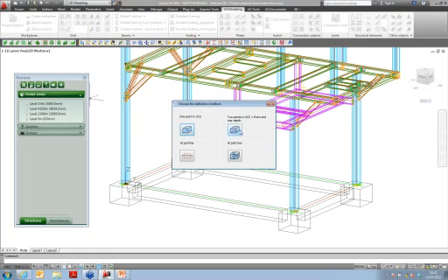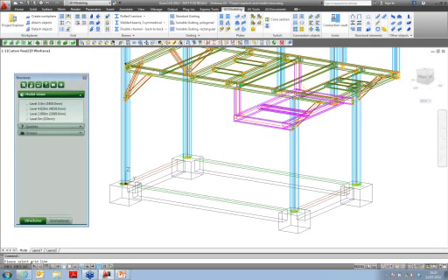You can also use this possibility to pick 2 points and to define the depth, but you can even pick a grid line or join both. Here, in my case, I would like to pick a green line, which is this one, the number 1. I press enter. As you can see here in the command line, you can enter a name. So it will be my elevation axis 1.